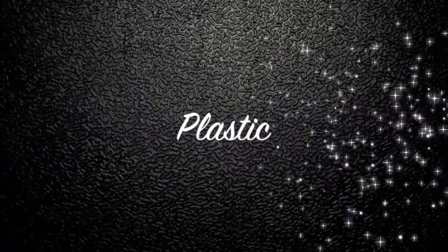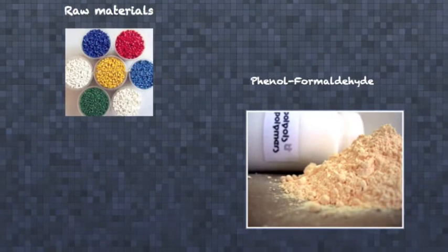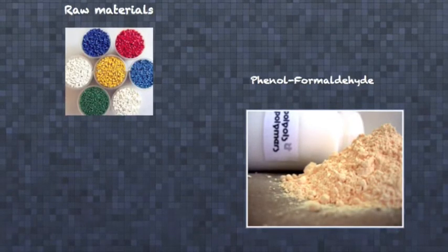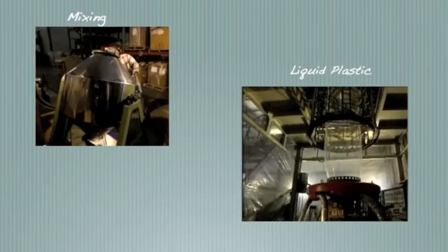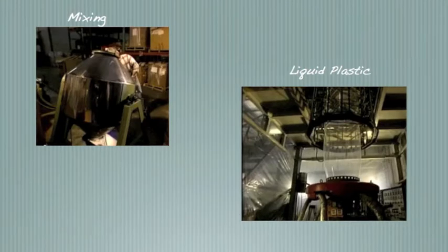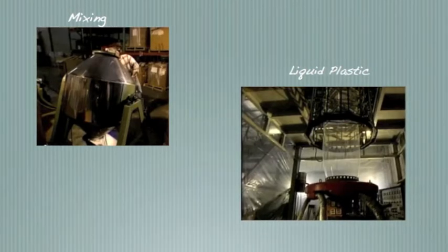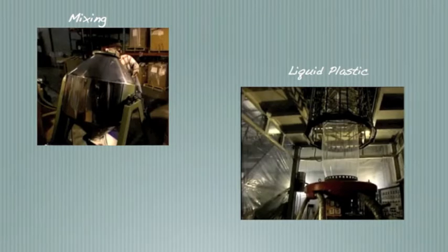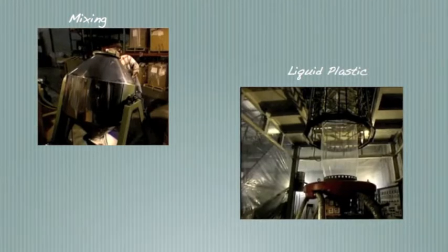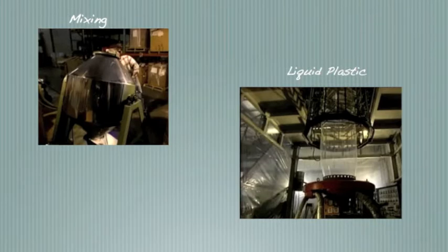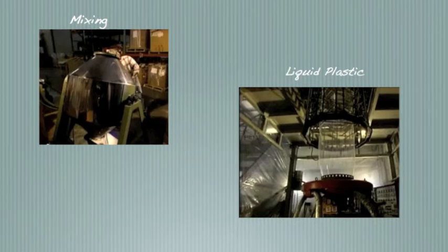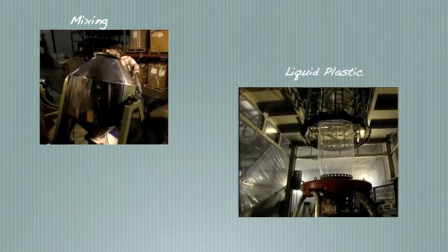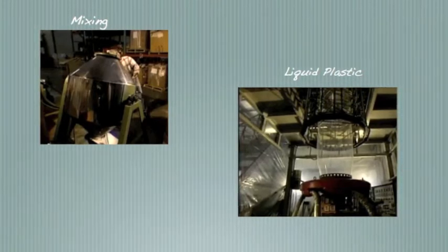My next material is plastic. Plastic is made of raw materials, styrene, mixed with chemicals like phenol formaldehyde. Starting by mixing styrene monomers together in stir tanks with other chemicals. Then monomers will change into polymers and be heated carefully in a vessel. A liquid plastic is dropped along a tube with a screw-shaped extruder and then shaped into whatever product they will use it for.